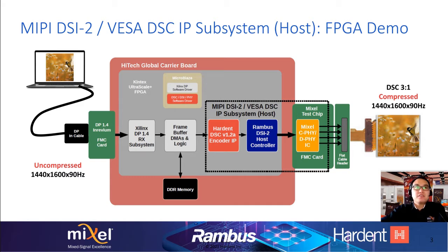We have chosen an AR/VR type of display from display panel maker BOE. It supports 1440 by 1600 resolution, up to a 90 Hz refresh rate, and a DSC decoding of a video stream compressed at a 3x ratio. You can see the display here on the right.